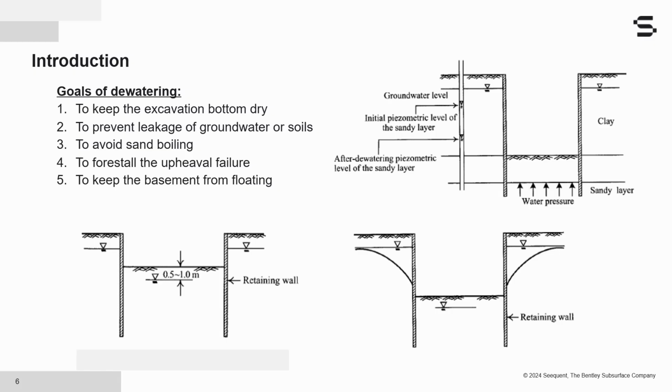Of course, many methods are available to avoid sand boiling. One of them is to lower the groundwater level outside the excavation zone. However, the possibility of ground settlement outside the excavation zone also has to be considered.